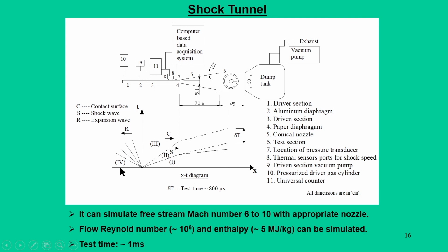Now, moving further, as I mentioned in my previous lecture, the shock tunnel is another high enthalpy facility, and it is nothing but an extension of a shock tube. If you look at this particular figure, the shock tunnel essentially consists of two parts. One is the shock tube part, and this is the tunnel part.